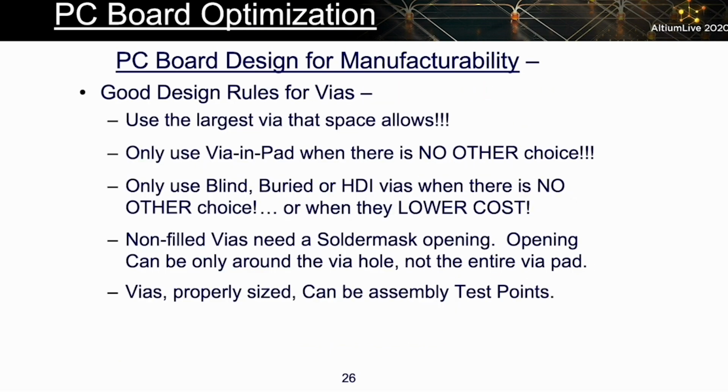Use the largest via hole that spacing allows. Good design rules for vias. Only use via and pad when nothing else will do. It makes repair and assembly harder. So do it only when you need to.